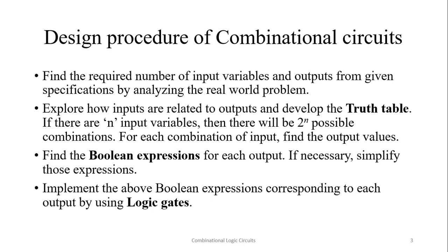If necessary, then the fifth step is simplification. If necessary, simplify these expressions. The last step is to implement the Boolean expressions corresponding to each output by using logic gates: AND, OR, NOT, NAND, NOR. So using exclusive OR, exclusive NOR, using these gates, we implement the Boolean expressions.